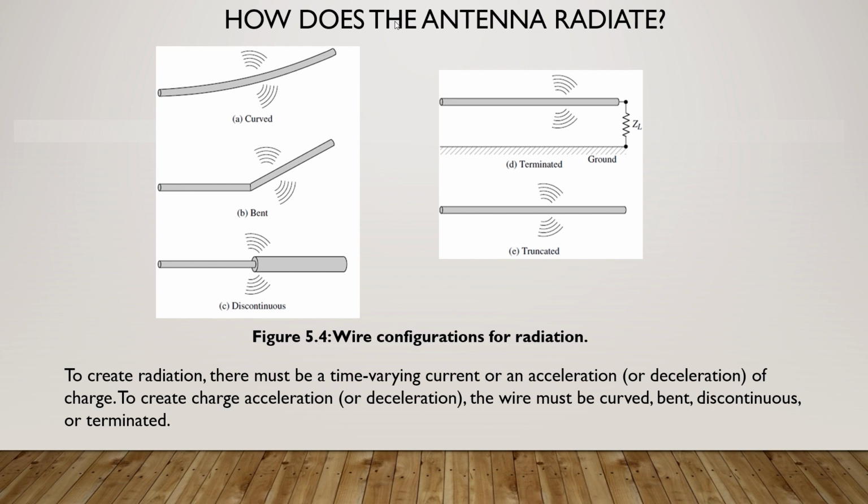The acceleration of charges is accomplished by external sources in which forces set the charge in motion and produce associated field radiation. The deceleration of the charges at the end of the wire is accomplished by internal forces associated with induced field due to the buildup of charge concentration at the end of the wire. The internal forces receive energy from the charge buildup as its velocity is reduced to zero at the end of the wire. Therefore, charge acceleration due to exciting electric field and deceleration due to impedance discontinuities or smooth curve of the wire are mechanisms responsible for electromagnetic radiation.